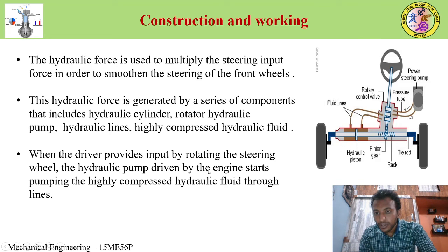So if you look at the sketch here, this rotary valve is placed between the steering wheel and the rack and pinion mechanism, which plays a very important role in this power steering. All this effort of this human gets reduced because of this rotary control valve.